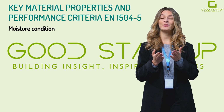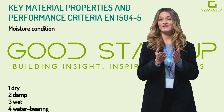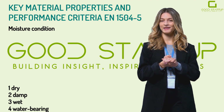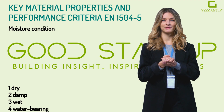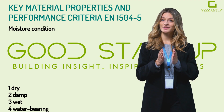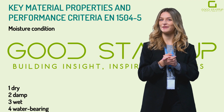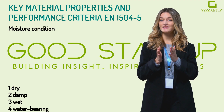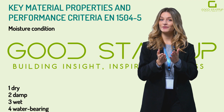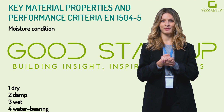Moisture compatibility. Cracks can be dry, damp, wet, or actively water-bearing. EN 1504 Part 5 classifies products by the moisture condition they are suited for. 1 equals dry, 2 equals damp, 3 equals wet, 4 equals water flow. For example, many epoxies are only suited for dry to slightly damp cracks, while polyurethanes can often work in wet or even water flow conditions. The product's documentation will state the allowable moisture condition. It's critical to use a material that can properly cure in the actual field conditions. Otherwise, adhesion or curing may be compromised.